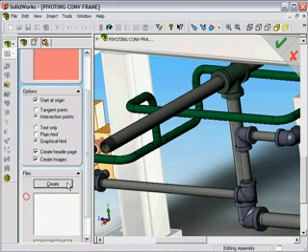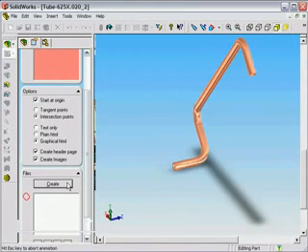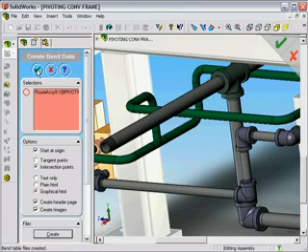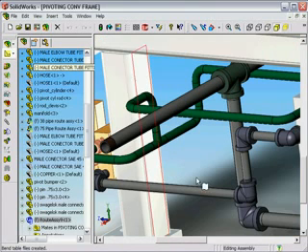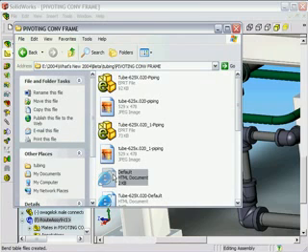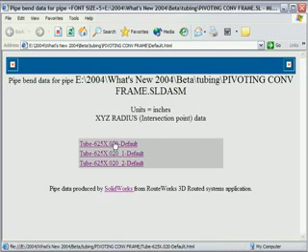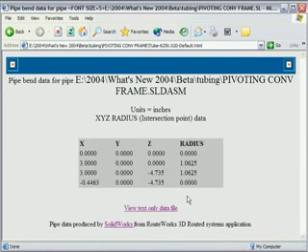You can see we have some various options. We're going to do a fully interactive HTML report representing all the necessary manufacturing information for our rigid tubing. Now let's take a look at that manufacturing information generated by SolidWorks Routing. You can see everything's placed in a nice HTML-based report.